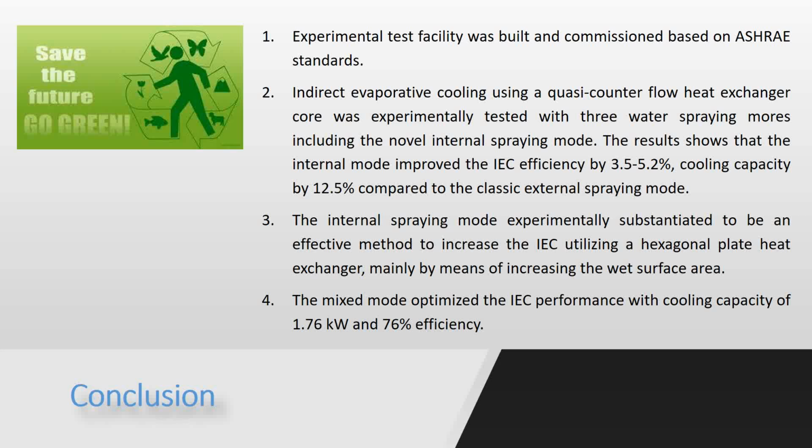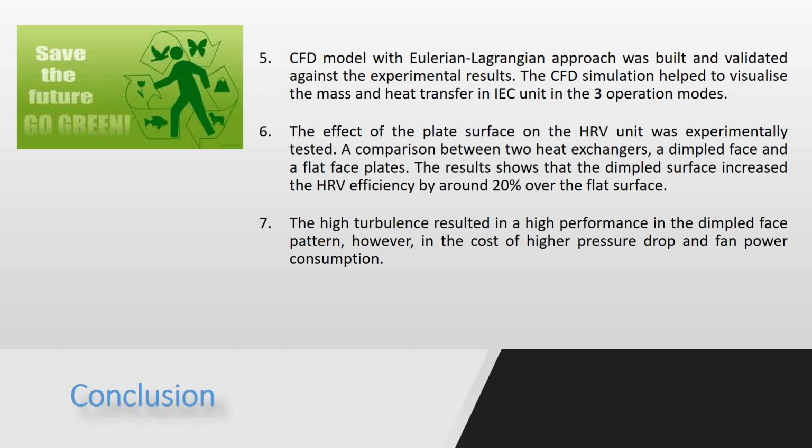The CFD model was built and validated against experimental results. The CFD simulation helped to visualize the mass and heat transfer in the IEC unit in the 3 operation modes. The effects of the plate surface with the HRV unit were experimentally tested, and a comparison between the two heat exchangers, the dimpled face and the flat face plates, was done.